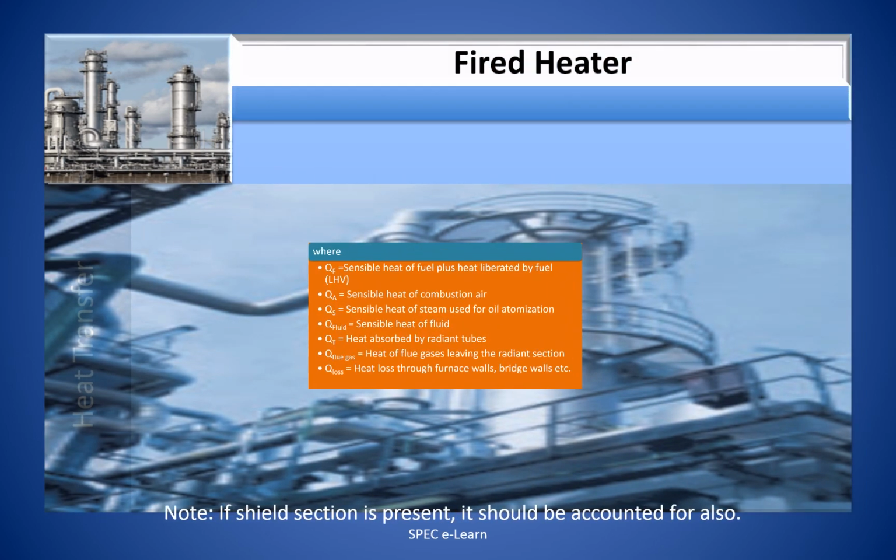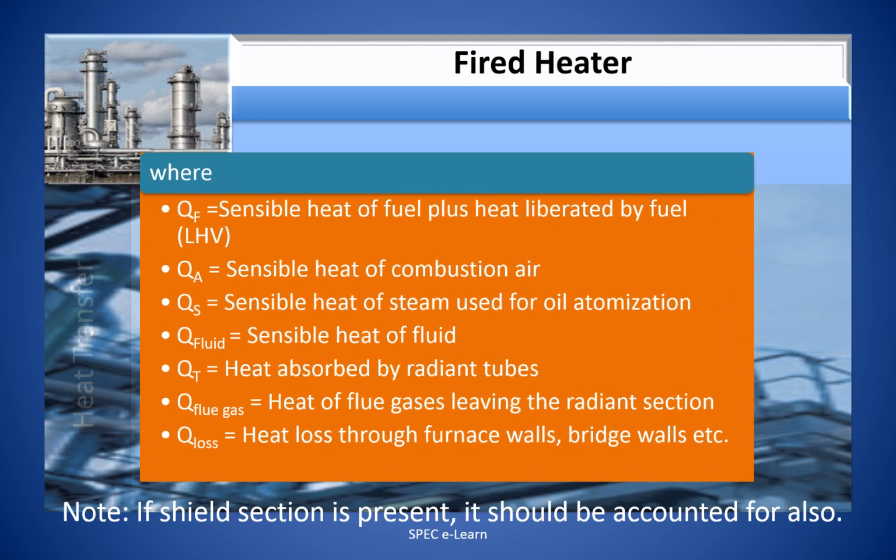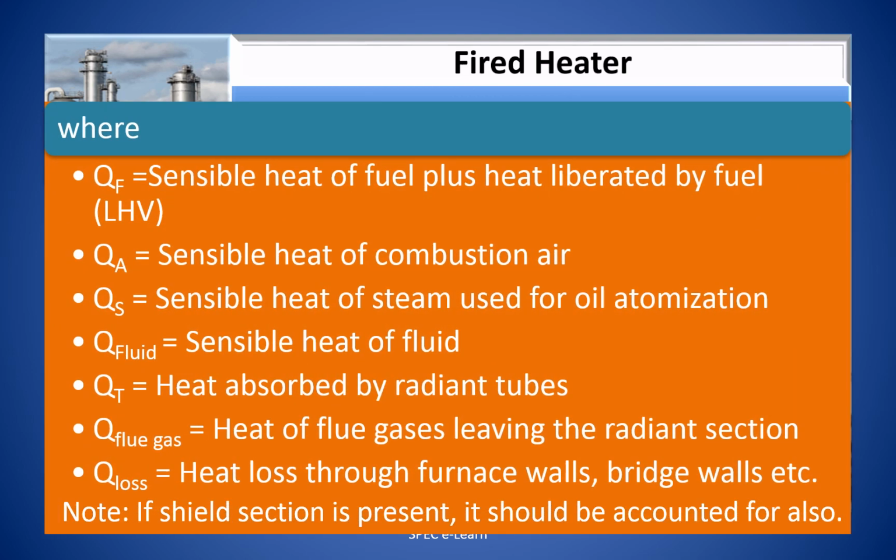Where QF is the sensible heat of fuel plus heat liberated by fuel, that is lower heating value. QA is the sensible heat of air. QS is the sensible heat of steam used for oil atomization. Q fluid is the sensible heat of fluid.